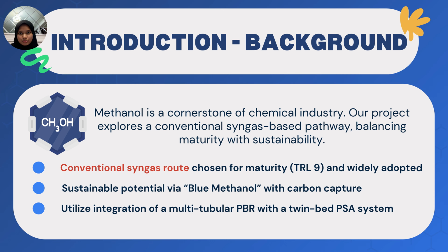And beyond conventional production, this route also opens the door to blue methanol, where carbon capture technologies can be integrated to significantly reduce the process's carbon footprint, adding a meaningful sustainability dimension to an already established pathway. And at the heart of our process design is the combination of a multi-tubular packed bed reactor, PBR, with a twin bed pressure swing adsorption system, PSA, enabling efficient methanol synthesis and effective gas separation and recycling.